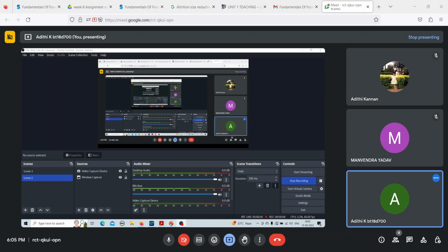So we need to calculate the fineness modulus, or how fine the particles are. In each of these sieve numbers, you have 10 grams of the product retained. In sieve number 50, you have 18 grams of product retained. In sieve number 30, you have 26 grams of the product retained. So these are all bigger in size, which is why they are retained. And in sieve number 15, you have 34 grams retained. And in the final collection pan, you are getting 12 grams.